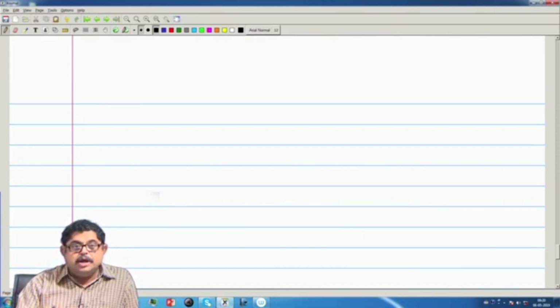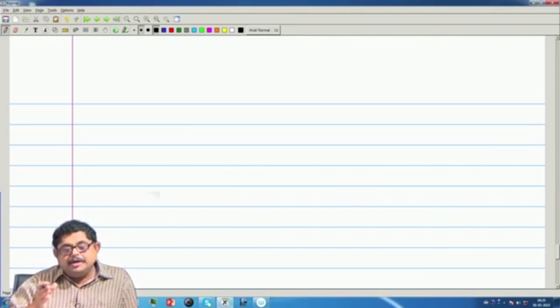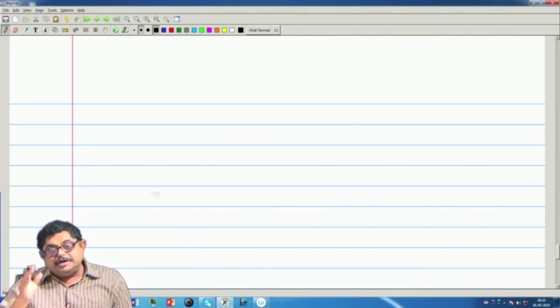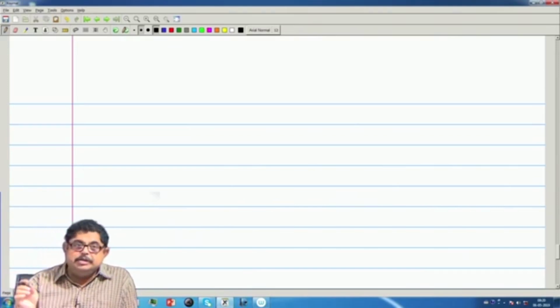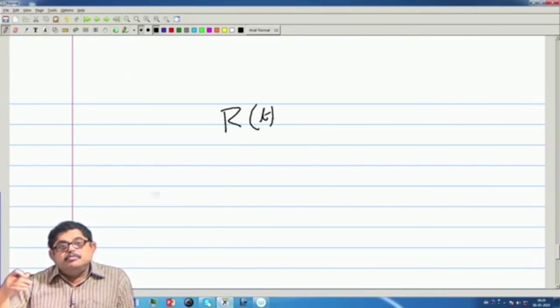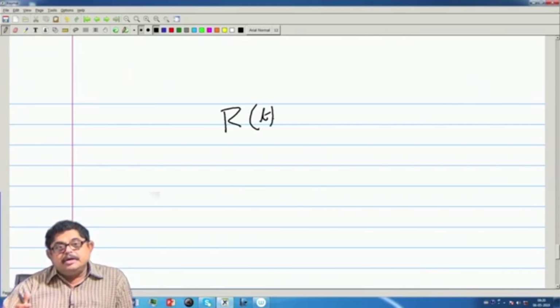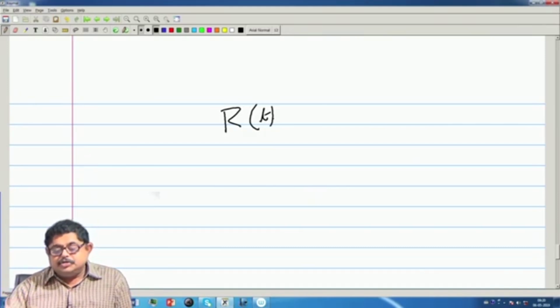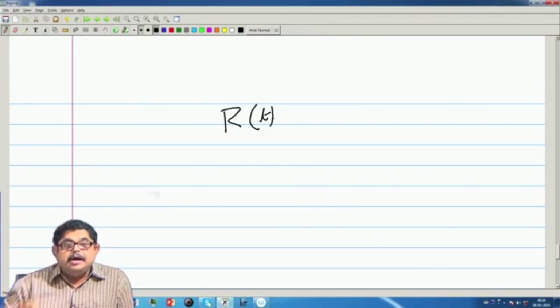The moment we put a pulse, the waveform has a timing mark. So, I can easily measure range, and if I measure R as a function of time, then I can differentiate this, because I have the timing information. So, if I know R(t), I can find velocity.